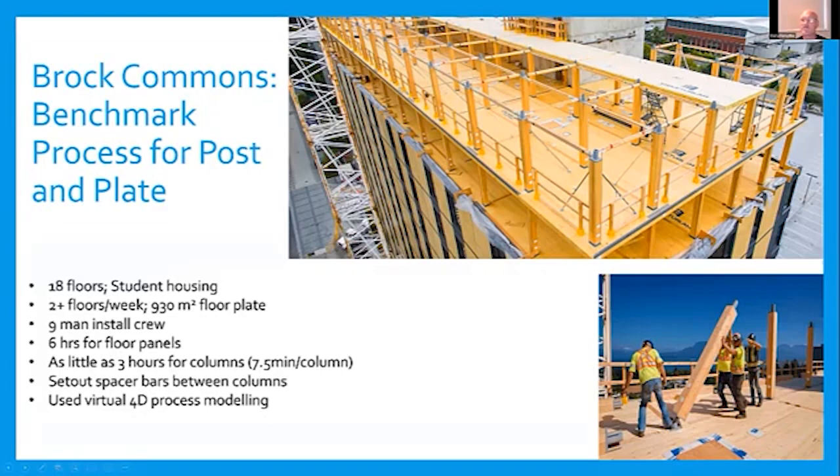So very easy, and you can see the spacer bars help hold the top of the column grid in place, which meant the columns were fairly rigidly located for landing these tabletop pieces. It meant that there was relatively little propping of the columns that you can see here. This was an 18-story student housing, and that's why there's such a close column spacing. It's not that different compared to, say, a jail cell.